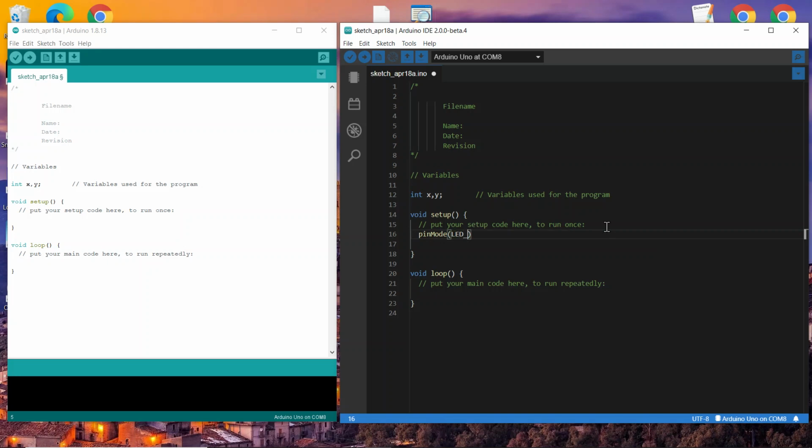They don't seem like they're assisting me too well right now, and I think as I type LED_BUILTIN, which is the light internal on the board, instead of giving it a specific number, it's the default light for the Arduino. That should come up, and it did before, and it doesn't right now, so a little disappointed, but that's a bug in the software.